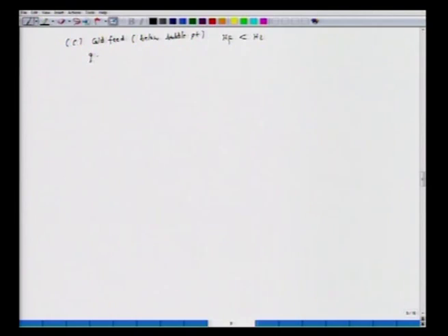So going back to the definition for q, we have q equals HG minus HF over HG minus HL, which from material balance is L bar minus L over F. q is greater than 1.0 because HF is smaller than HL. So that means the slope of this q line, which is q over q minus 1, will be greater than 1.0.